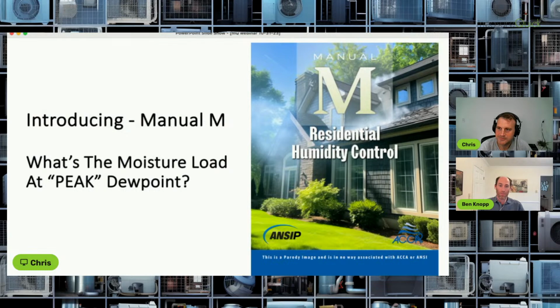So I know manual LLH, low load home, touches on this, but I think we need a manual that focuses on, does your equipment meet the load at peak dehumidification conditions or peak dew point conditions. That's when it's really not as hot outside as it is in the hottest part of the summer, but it's very humid. I'm sure we've all experienced that. It might be 75 degrees outside and pouring down rain for a week. You don't need to run your AC. You don't need to run heat. But you need to remove gallons and gallons of water.